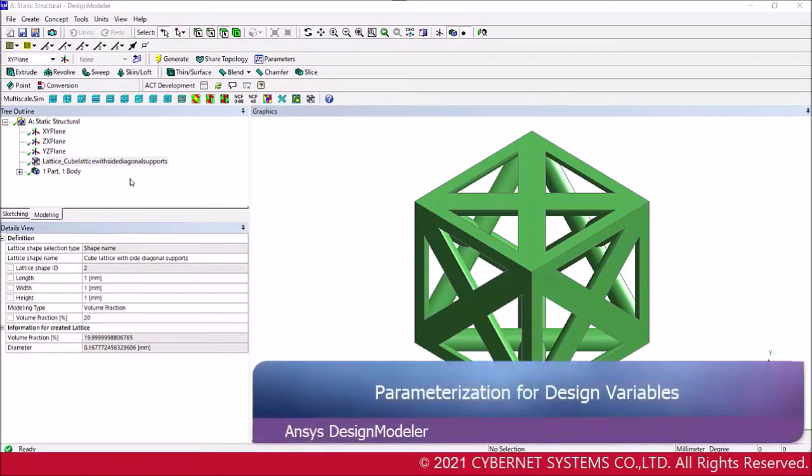So far, we have shown the analysis procedure for the single condition. Next, we will demonstrate the operation of parametric simulation. In this analysis, the input and output information we want to change needs to be parameterized. Typically, this information is referred to as design variables. This time, we will set the lattice geometry parameters as design variables, specifically the lattice topology and height, and the volume content of the columns.